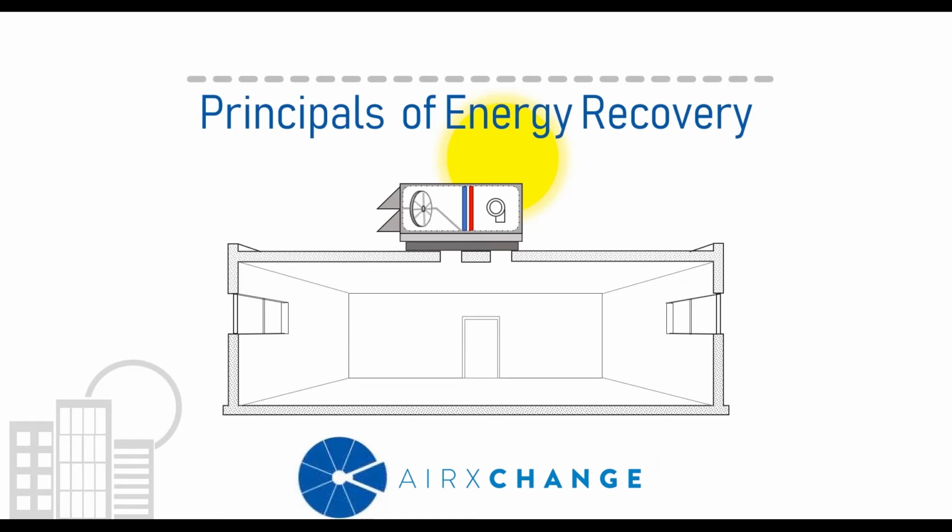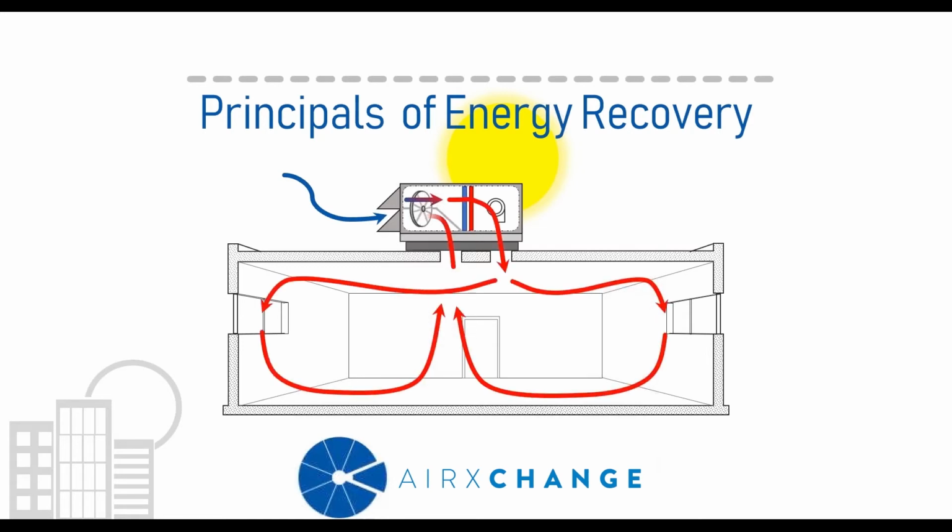Now, let's look at that same process, but adding an energy recovery wheel to that system. So instead of the primary heating element having to treat the entire ventilation load, the energy in the exhausted air performs a large portion of the work, which reduces the capacity required by the primary heating element to do the same amount of work. I often refer to this process as a load shift, where you're shifting the heating load over to the wheel and still accomplishing the proper ventilation to the space.